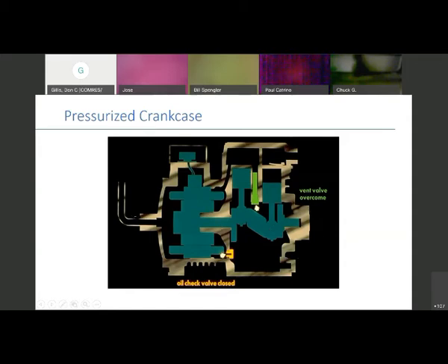So what we want you to do is hook your gauges up right here at the suction line, right before entering the compressor on this refrigerant cooled model. There's a plug on the side of this compressor. We're going to ask you to remove that plug and put a brass fitting in. It's like a 1/2 by 1/2. You'll have a flared fitting on one end for your refrigerant hoses. So you're hooking up a refrigerant hose here and a refrigerant hose here.